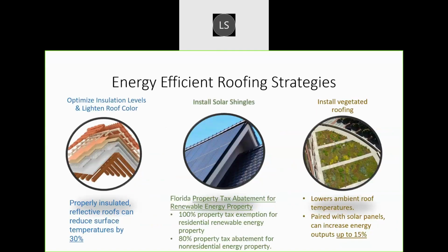Next slide. Another way to improve energy efficiency, of course, is to improve the functionality of our roofs and use them to generate the energy that we need. For example, optimizing the insulation levels and lightening the roof color. Re-roofing is an opportunity to update the insulation levels if possible to better preserve the energy within the home. And there are also energy efficient insulating materials to consider now, such as polyiso, which can be recycled and reused on roofing applications.